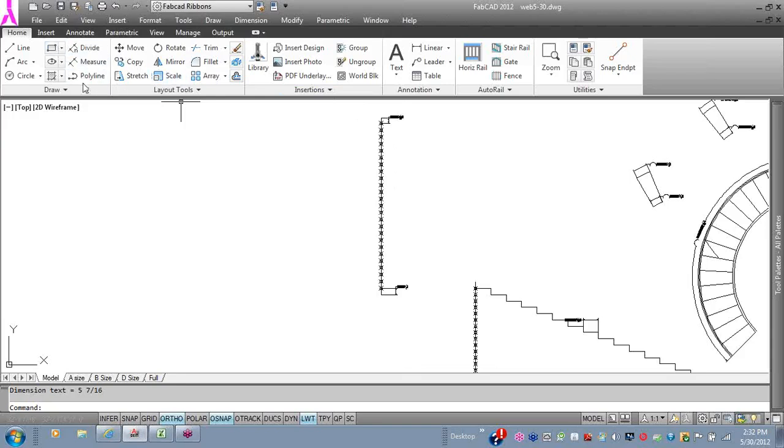So then I go through and use the erase command, let the computer count them, and then put a window in so that I know exactly how many nodes. I got 25, which means I divide this line evenly by 26, and I've got evenly spaced risers, not exceeding whatever I put in on the measure command. That's how you do that.